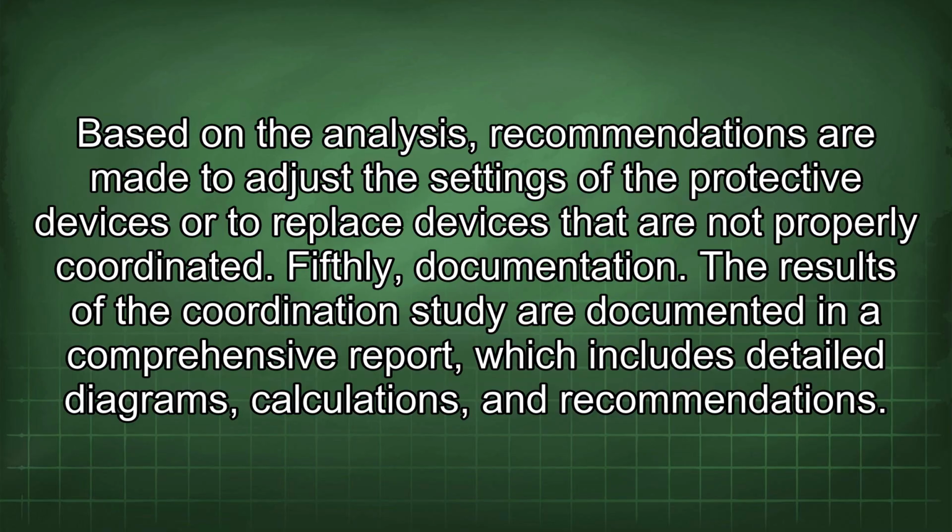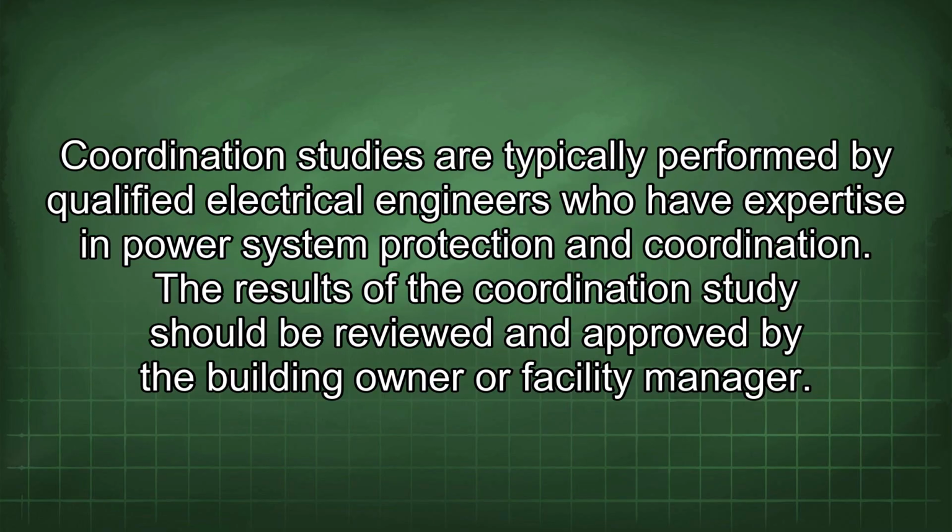Fifthly, documentation. The results of the coordination study are documented in a comprehensive report, which includes detailed diagrams, calculations, and recommendations. Coordination studies are typically performed by qualified electrical engineers who have expertise in power system protection and coordination. The results of the coordination study should be reviewed and approved by the building owner or facility manager.